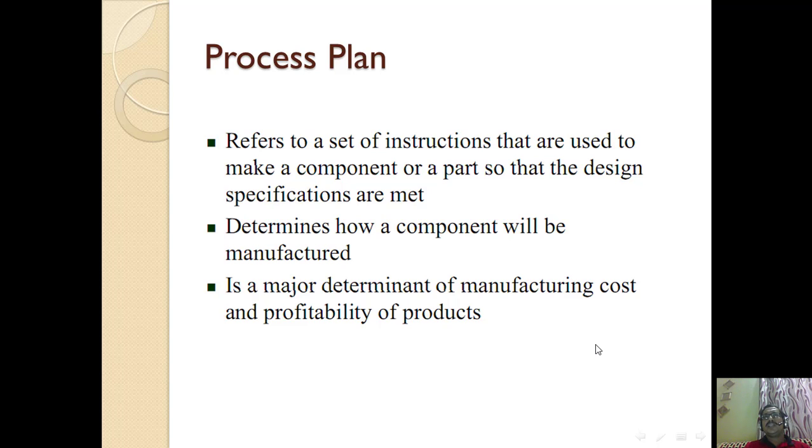So for standard time, let's say a particular expert gives a standard time of 3 minutes, and somebody gives 3.1 minutes. So 3.1 minutes means 0.1 minute more in your cycle time, but if you want to manufacture a huge number of products, then your productivity will be delayed. So you have to plan your cycle time accordingly, to find the minimum cycle time that gives the better result. So the best sequence and minimum standard time you have to fix.